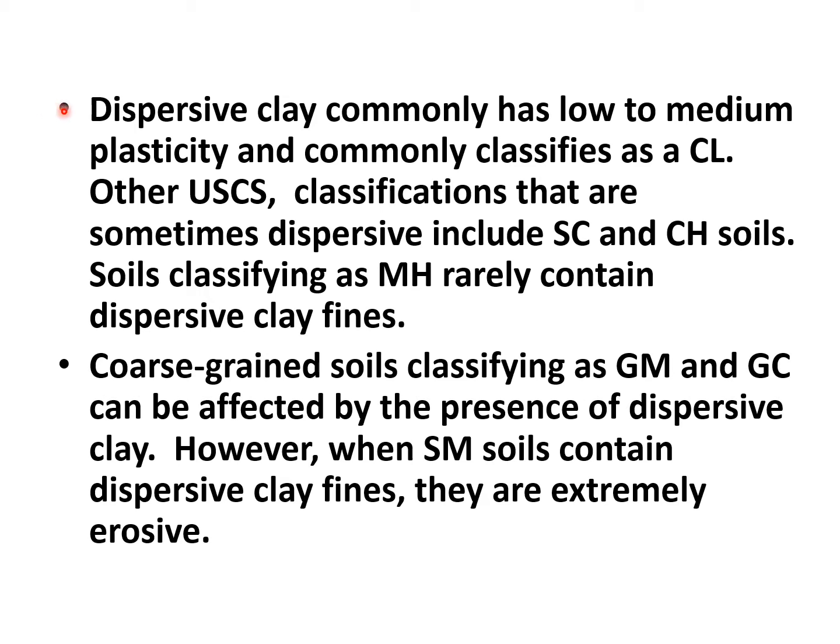Dispersive clay commonly has low to medium plasticity and commonly classifies as a CL. Other USCS classifications that are sometimes dispersive include SC and CH soils. Soils classifying as MH rarely contain dispersive clay fines.